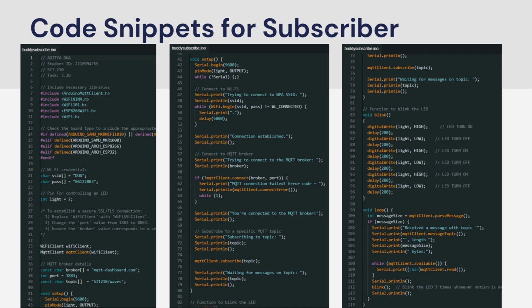At last, the loop function operates in a continuous loop, constantly checking for incoming MQTT messages from the client. When a message is detected, it first prints details about the message, including the topic and size, and then proceeds to read and display the message's content. Furthermore, upon message reception, it triggers the blink function, causing the LED to blink 3 times. This loop continues to run continuously, monitoring for new messages, ensuring a responsive interaction with the MQTT broker.